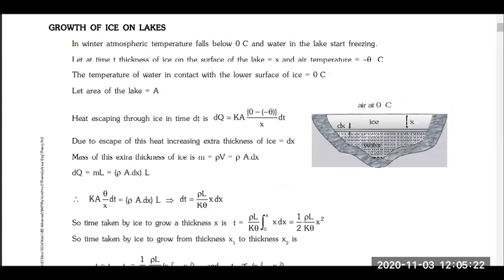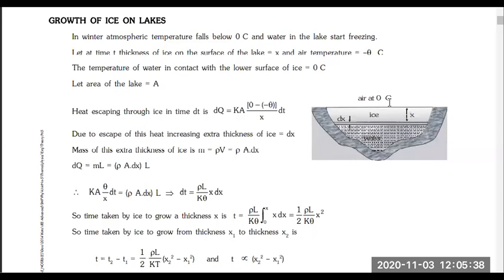Yes. Now there's another concept which is based on conduction. Now this is the temperature. What should the temperature difference be so that there will be development of ice at the center, and after what time will it get solidified and all those things? Now let's start with our basic definition, our basic equation of heat transfer. Now suppose the thickness of ice is x, and we'll take an elemental area dx.